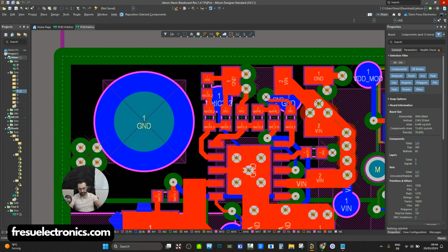And this is important because we have the inductance, which is dependent on the frequency. Also, this voltage drop is important not only for one IC. If we have a voltage drop in the power delivery network, then this voltage drop would be perceived also by all the other ICs, and we don't want that.